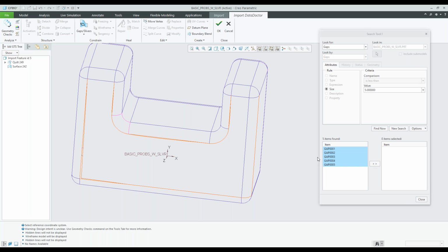And then all you quickly do is a quick find for gaps, and you use your geometry checks, and you will get a quick sense of where you are with the type of import you did. Another thing that can give you a quick indication on where you are with the components is if you search for one-sided edges.